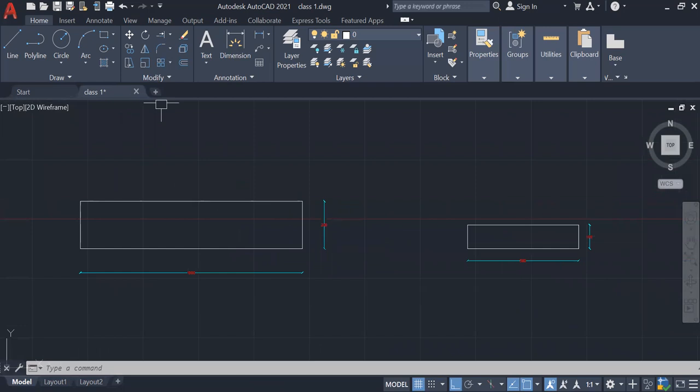You just remember, in both the directions we are using the scale command, that is in the x and in the y direction. And at the same time, for the reduction factor, you just remember, if you want to enlarge that one, we need to use a factor more than 1, and if you want to reduce that one, we need to use a factor between 0 to 1. Okay, so 0.9, 0.8, 0.75, 0.5, 0.1, 0.01, 0.001, 0.009, like that. Depending upon the scale factor, we need to use that one.